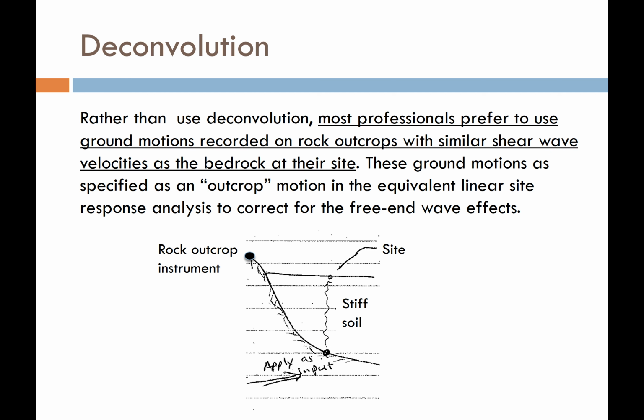But I guarantee if you get into this line of work, you're going to come across engineers who use deconvolution routinely, religiously, and they're going to swear by it. So you kind of have to be careful there. You don't want to step on any toes. And again, this is the key. When you plug these things into their software, please make sure that you specify to the software that you're dealing with an outcrop motion.